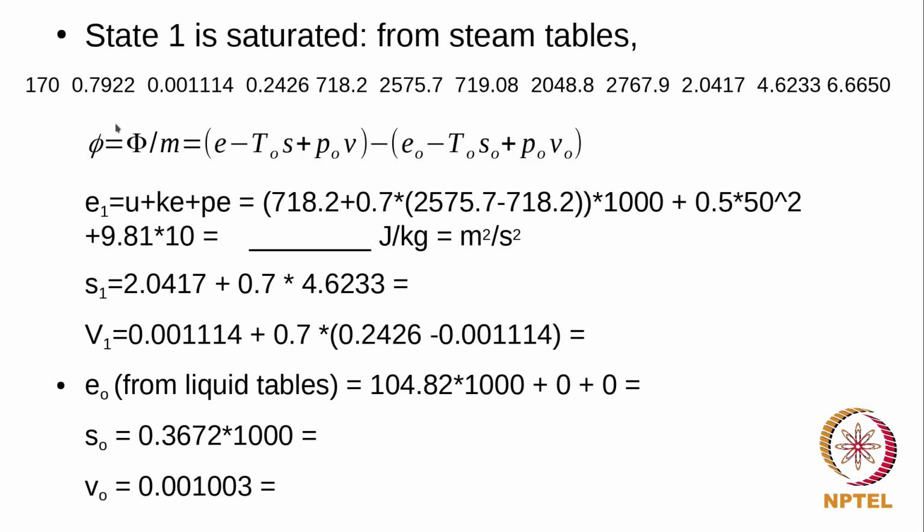So whatever is the Exergy value will tell us that supposing this steam was used in a reversible process and it was brought to the dead state, that is the amount of work we would be able to extract from this. What is also usually interesting in these cases is to compare the contributions of different terms towards the Exergy. So this is the total Exergy.